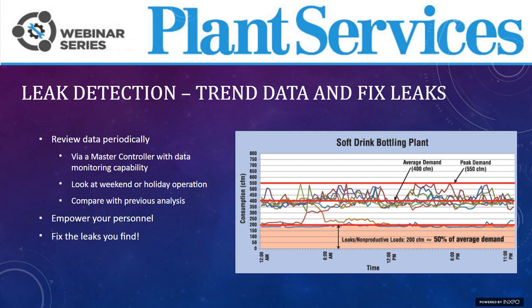A quick anecdote: when we were touring a facility with maintenance personnel, we found a quarter-inch ball valve on a large receiver that was wide open. When we asked the maintenance person, he said, yeah, we leave it open all the time. And we asked why. They astutely said that the tank had entrained a lot of water, which passed downstream and led to product scrap. So we asked what their limit was for a purchase order, and they said something like $500. When we told them that this particular leak on this particular ball valve was costing the plant upward of $10,000 per year, they quickly purchased a no-loss demand drain.